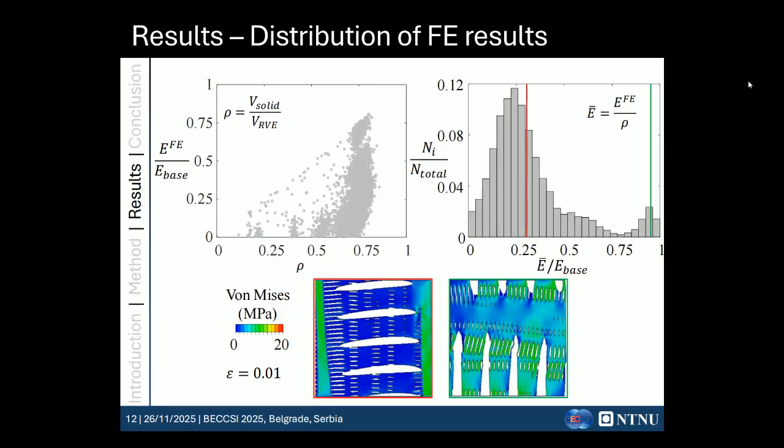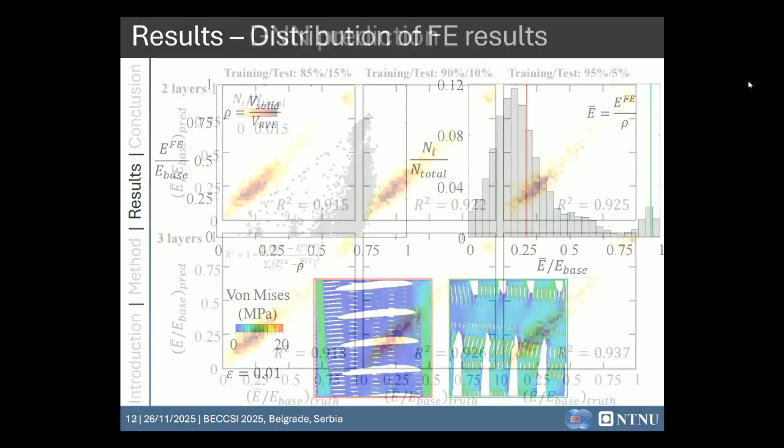And by looking at these stress contours, we get a meaningful result: by putting more material taking the load along the loading directions, it should provide higher non-dimensional stiffness, and if there is less material along the loading directions, the non-dimensional effective stiffness of the whole structure would be lower. So this confirms our studies.